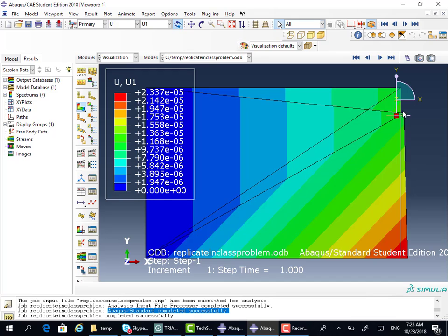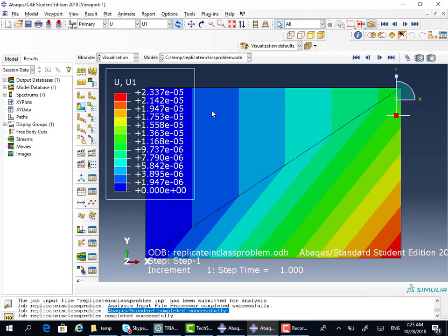So here, this is the original. Then you see this node move here. This node moved along the x, but not in y. So it's fine. So the displacements look accurate. Now notice that you get contour results within the element when you see the displacement field, and that is accurate. The displacement should change along x and y.